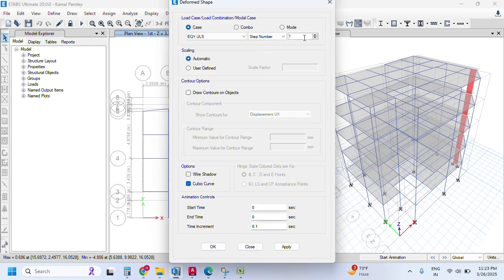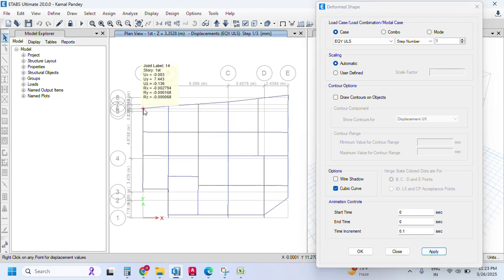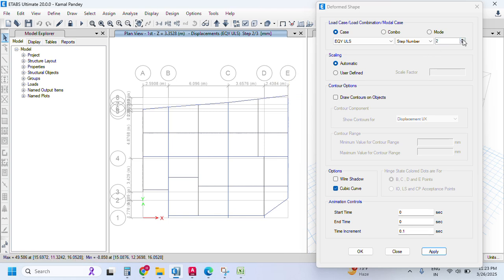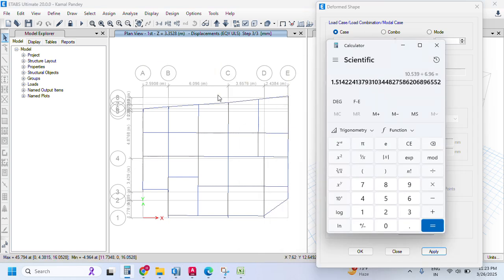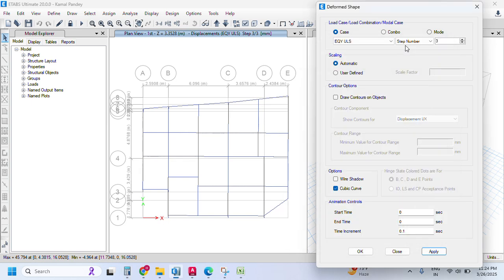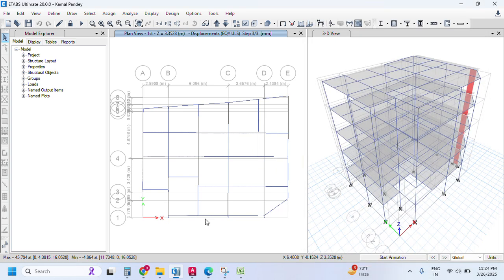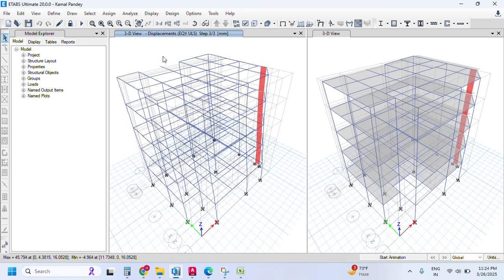Go to QY, since there was a problem in the Y direction. 7.44 upon 6.33. The ratio of 7 to 6 is less than 1.5. Okay, check in mode 2 as well. 6.55 upon 7. Okay, this is also within the permissible limit. In modes 3, 5, 8, let's check: 8.335 upon 5.732. Okay, it is within the permissible limit. In this way we can remove torsional irregularity.